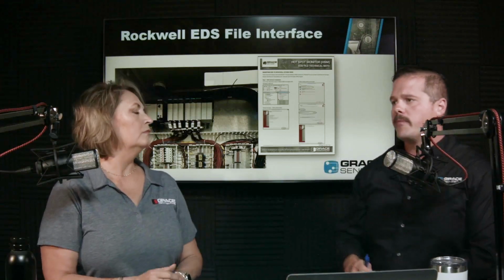So just double clicking on that for a minute, you need to be able to put the base unit, the module, in a hazardous location rated enclosure. The fibers are non-conductive, and so there's no power running to those sensors. They are not really intended for outdoor use, though. Well, they're not UV rated. Yep. However, most people just put them in a conduit of some kind, even if it's a flex conduit, just to give it a little bit of protection from the UV.